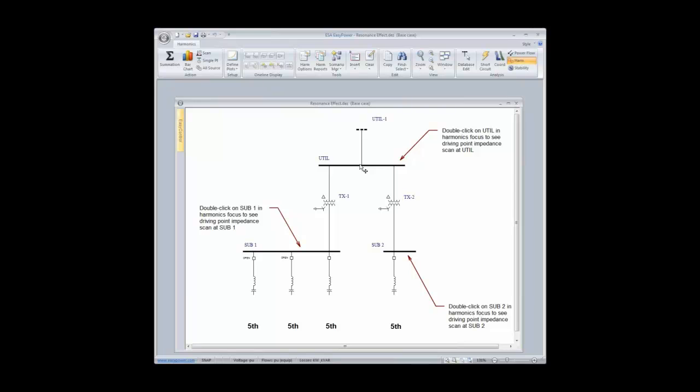And when I did my grunt work underneath him and I was cutting my teeth, he would tell the story of a utility applying a large fifth harmonic filter at a point in their grid because they had this issue and they wanted to kind of shunt off some of that fifth harmonic current. So they designed it. They designed what size the capacitors and the reactors would be for that filter. They put the thing online, and it quickly exploded. And the reason why it exploded was very simple: it absorbed every fifth harmonic current on the whole stinking utility grid for around 100 or 200 miles.